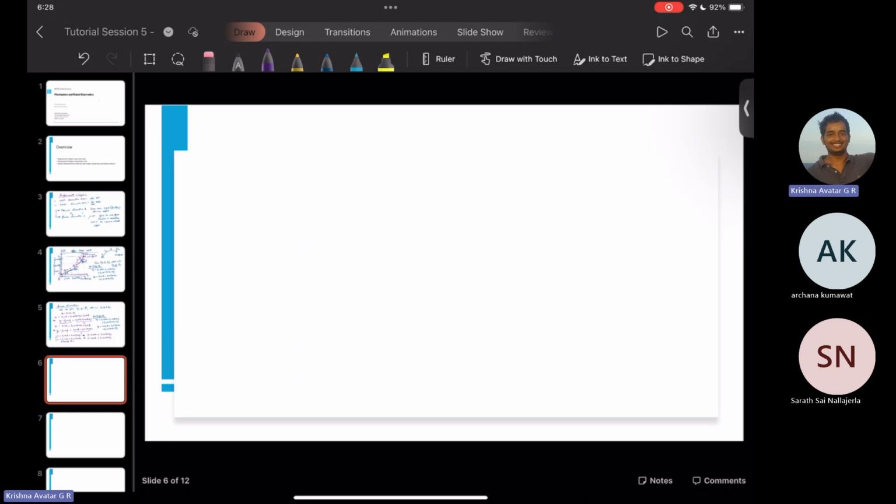So given that we have X minus L1 cosine theta 1 is equal to L2 cosine theta 1 plus theta 2, and Y minus L1 sine theta 1 is equal to L2 sine theta 1 plus theta 2, what we can do is eliminate theta 2 from these equations.